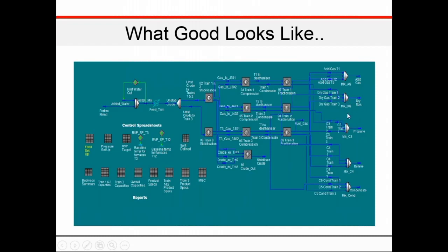And from here, if you right click on the design simulation platform, you'll be able to tell more properties of each of these streams: their flow rate, their temperature, their pressure, those variables that we mentioned before. When you see it showing dark blue like this, it means these streams have already been solved.